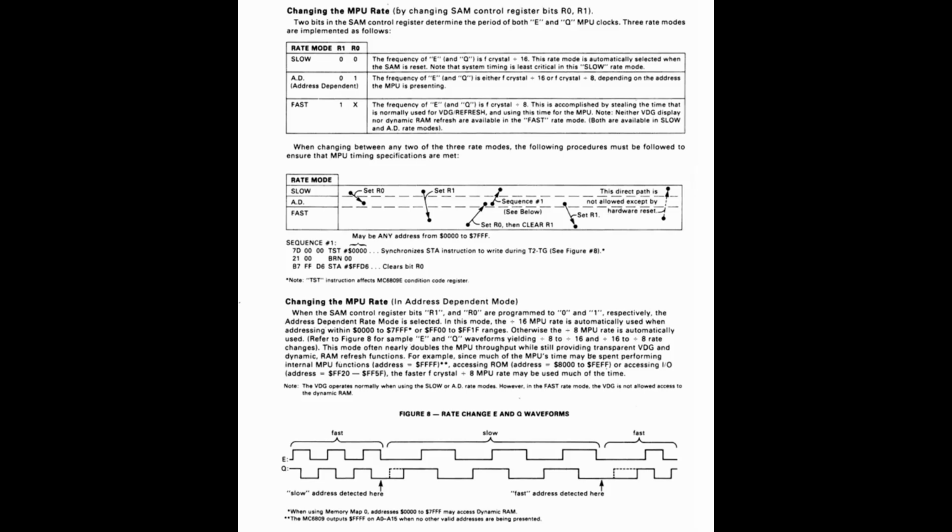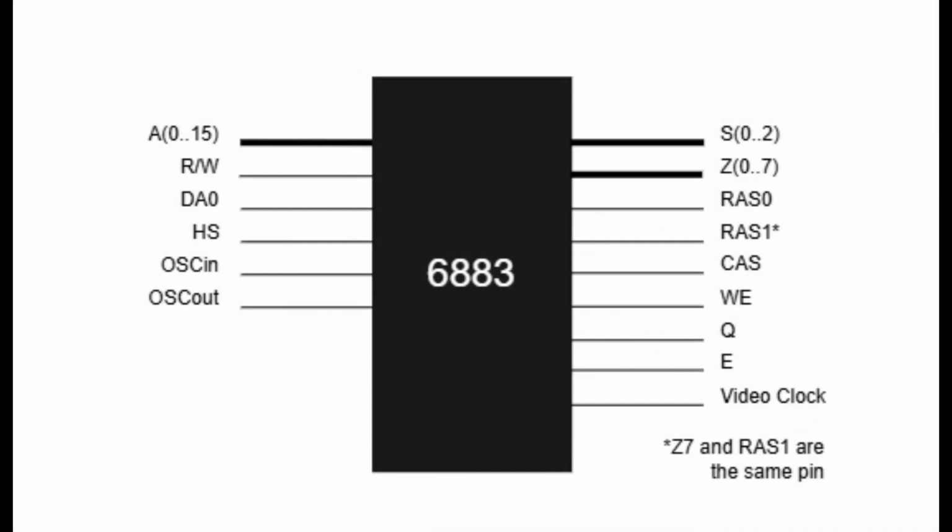Keep in mind that many instructions have dead cycles in terms of memory access. In full fast mode, neither the video access or RAM refresh are performed. Video is still generated, but it will be garbage, and in theory, unless in SRAM mode, the system memory should corrupt pretty quickly.